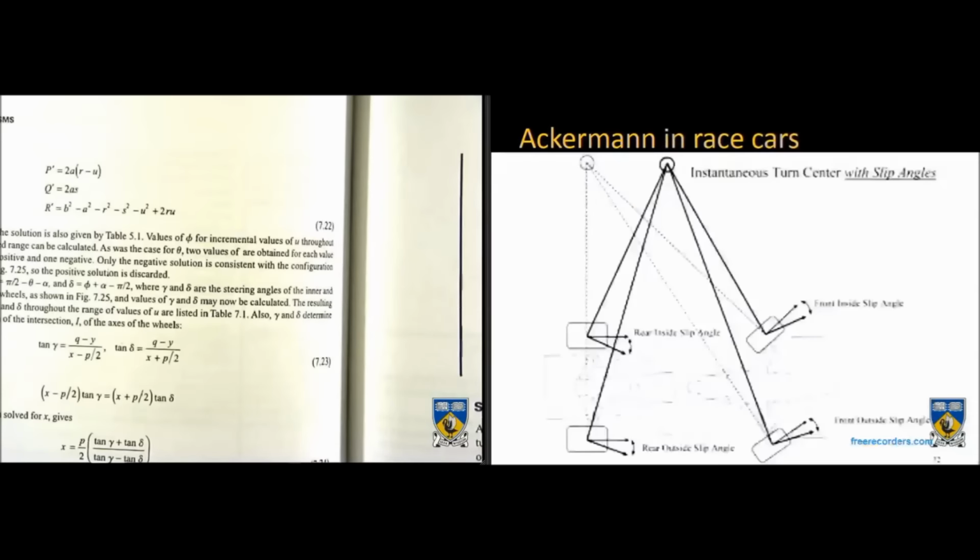Here we go. So you can actually see now, if you introduce slip angles to the equation, the dotted line represents no slip angle, so your theoretical Ackerman. You introduce slip angles again, and the wheel's force direction is changing, and the black lines give you your true radius of curvature or center of rotation. So it's really important. This is the slip angle, probably only 5 degrees, but it has quite a significant change on the aspects of what's going on in the car.